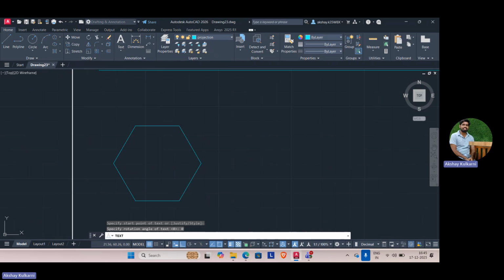So 0, enter. Now I'll give the names A, B, C, D, E, F. Click away somewhere and press escape, which comes out of that command.